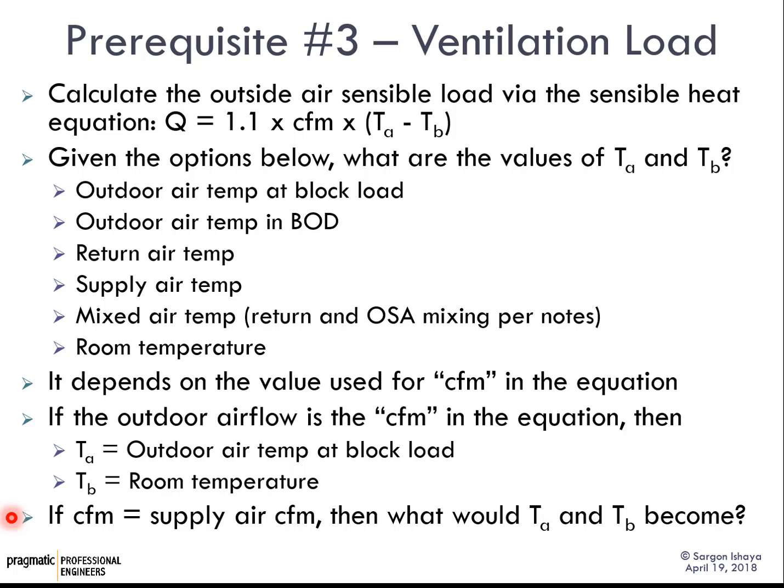If you use the total air conditioning unit's airflow in that CFM, then T sub A is still the outdoor air temperature at block load, but T sub B becomes the mixed air temperature, not the room air temperature, not the return air temperature. Think about that.